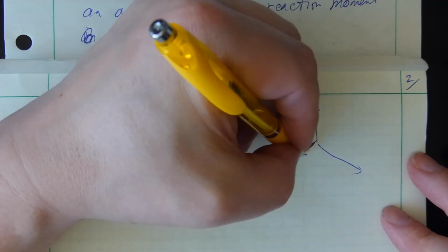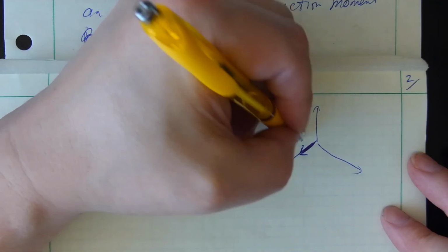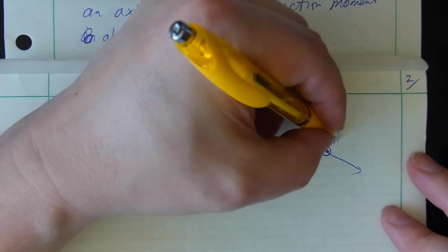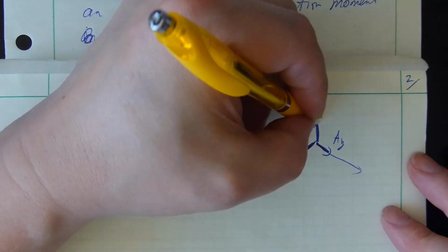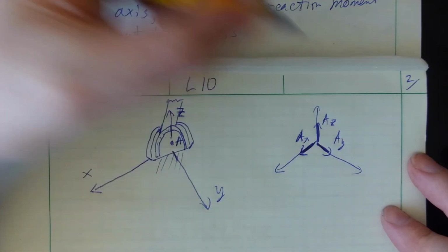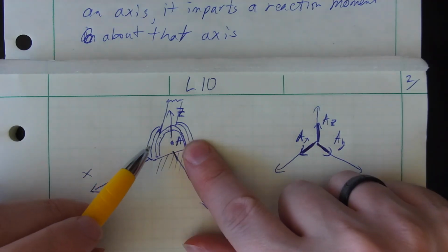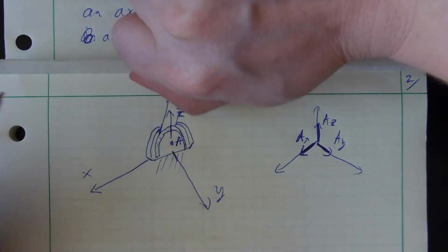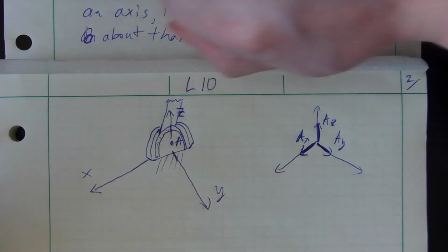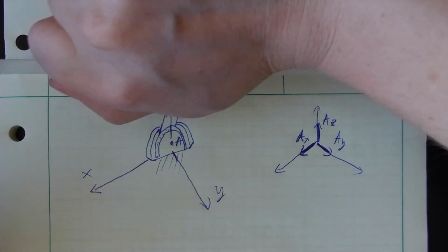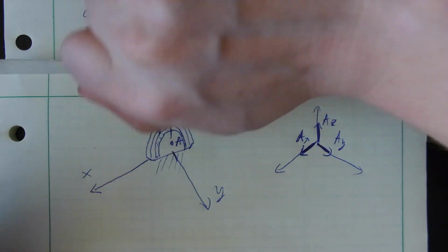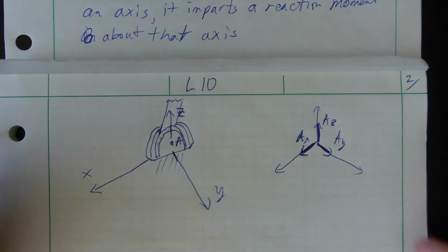You would have a reaction force in the X, a reaction force in the Y, and a reaction force in the Z, because this pin cannot come apart and you can't move it. If I grab this, whatever this is attached to, and try to pull it up in the Z direction, or move it in the X direction, or move it back and forth in the Y direction, it won't move. It's locked in because it's pinned in there. So I've got a reaction force in all three directions.